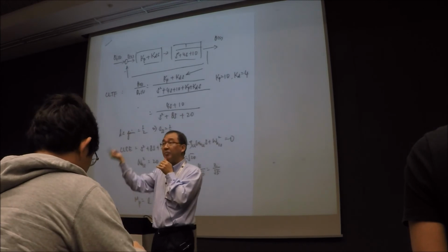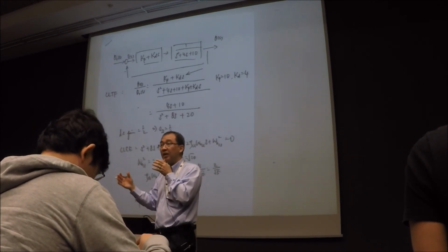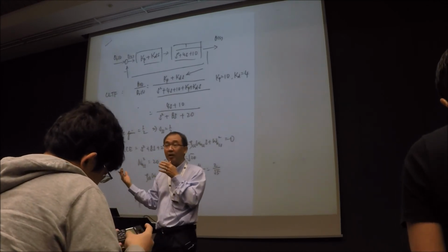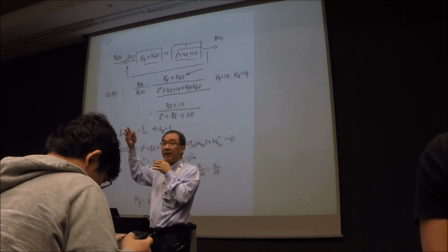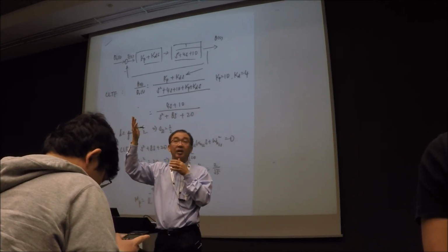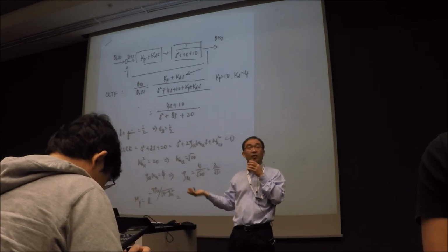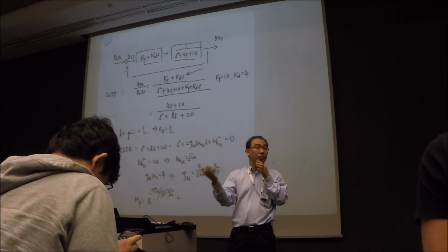So can you work backward? If you are given undamped natural frequency and damping ratio, you work backward to find out what will be your closed loop Kp and Kd. This is something that most likely sometimes tests you in the exam. Not always do they give you the number. They will always like to work backward to find out.